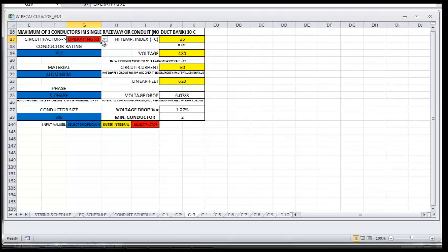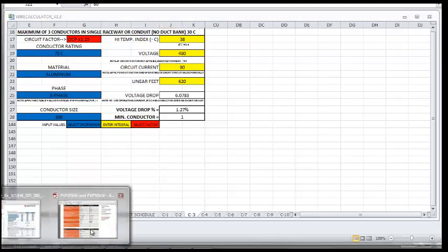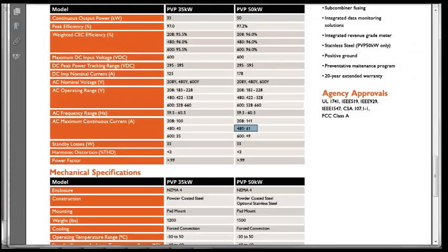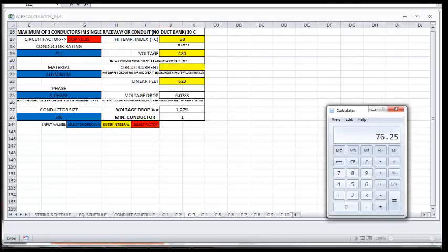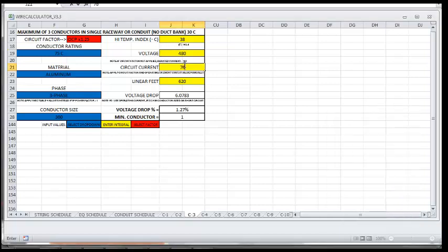Okay, we see the wire size matches. Okay, let's go into an AC calculation now. So 1.25 is our new factor. It's three-phase based on the inverter that we're using. We keep aluminum conductors. Okay, so we get our current from there. Design current, voltage drop current are both operating, so those will be the same field. There's no need for two separate fields there. Okay, so there's our design current.